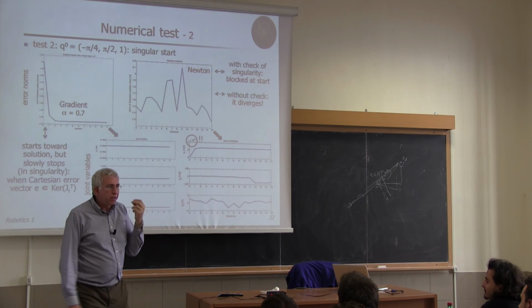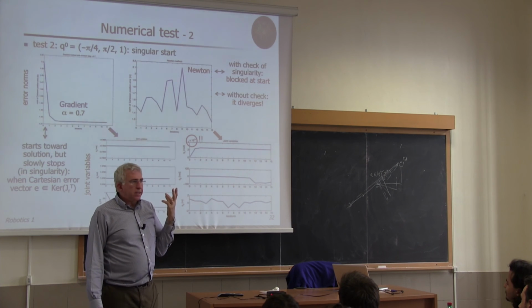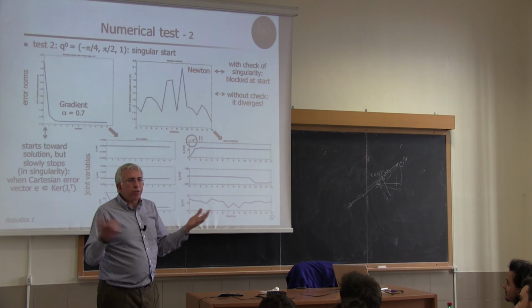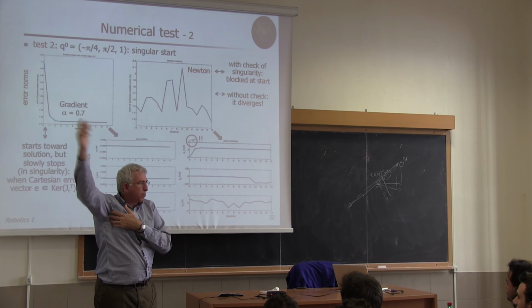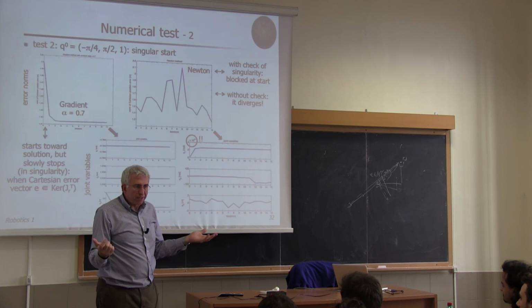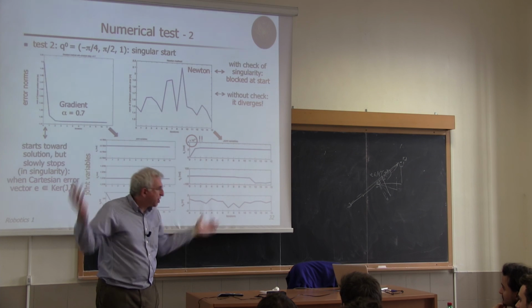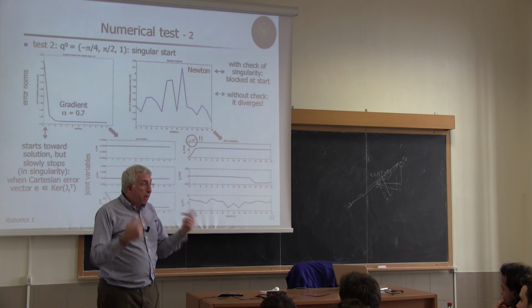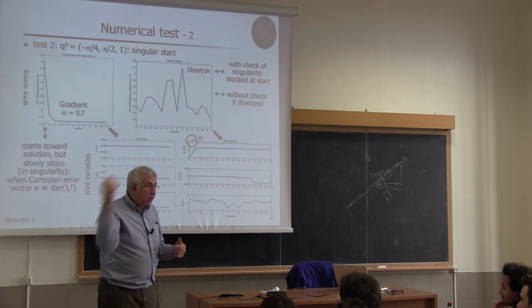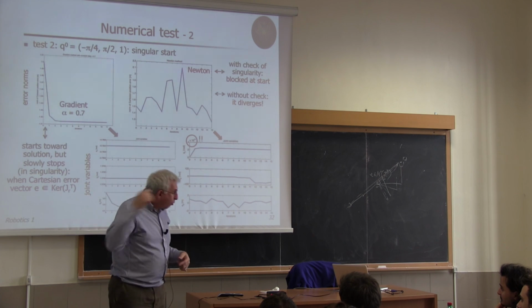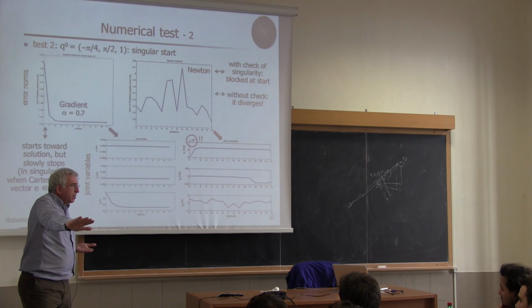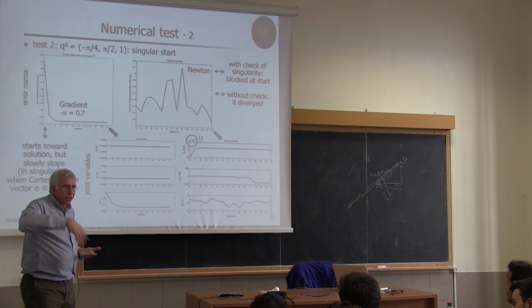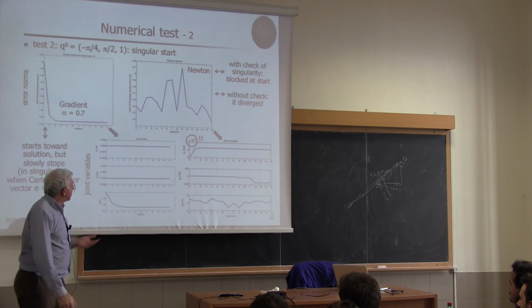Even if you think about the Cartesian space, with all revolute joints you cannot go much farther away. You always stay in the primary workspace, so the Cartesian error cannot increase more than a certain value. But in the joint space, you can increase the error because the joints start to fold and fold and fold, and you're considering this as a real axis. So you're not saying that after 2 pi you are in the same configuration. You're increasing pi and pi and pi.